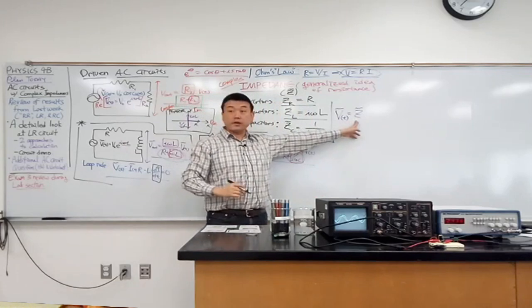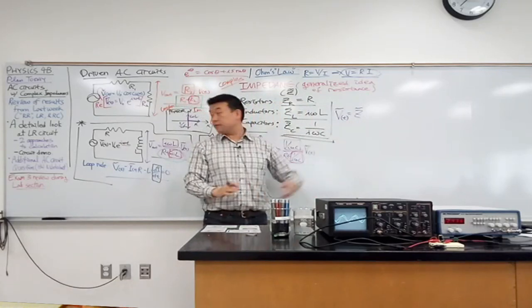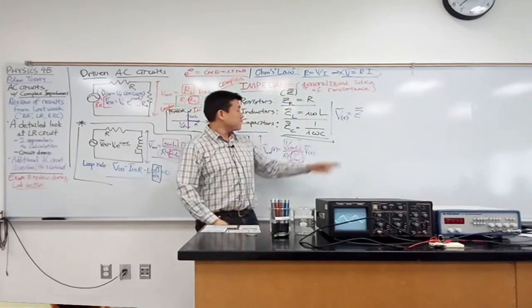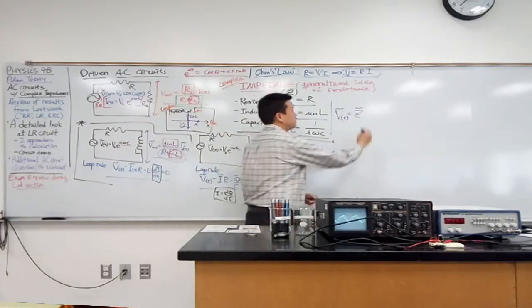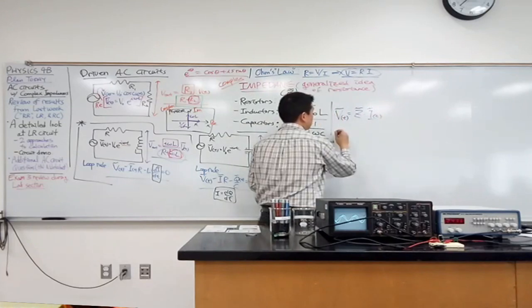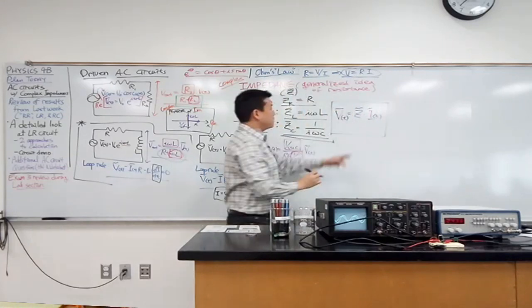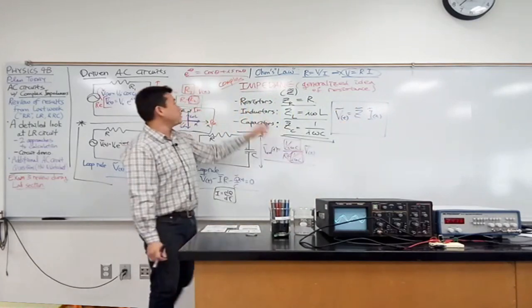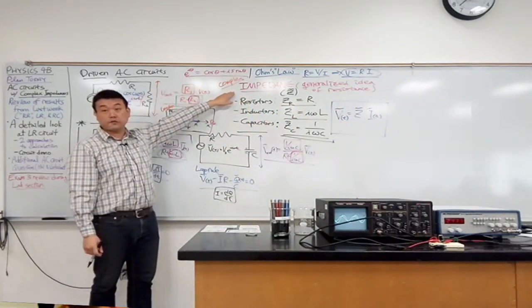It can be imaginary, real, complex. If we have two circuit elements in series, you can get complex impedance. So voltage will be impedance times current as a function of time. So this is a relationship. This linear relationship is what we are trying to restore, and that is the motivation for introducing this idea of impedance.